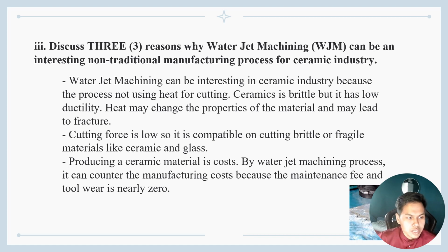Number two, the cutting force is low, so it is compatible for cutting brittle or fragile materials like ceramic and glass. Last one is that producing ceramic material by the water jet machining process can counter the manufacturing cost because the maintenance fee and tool wear are nearly zero.